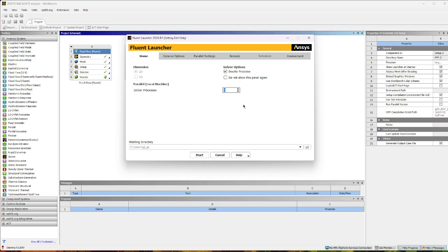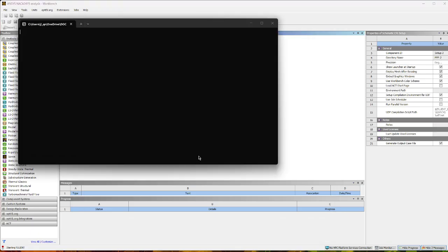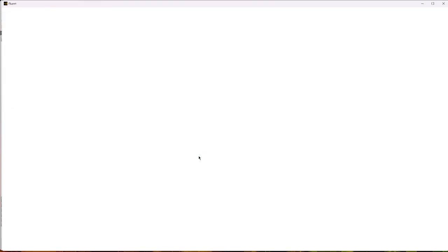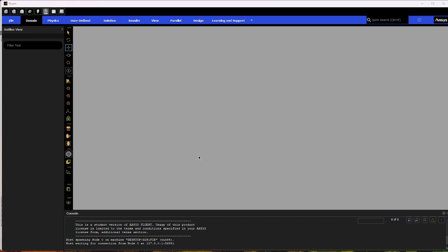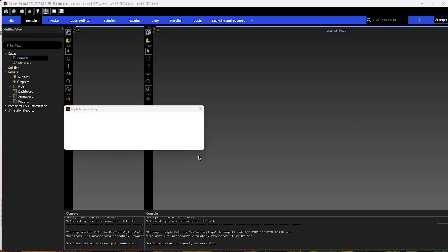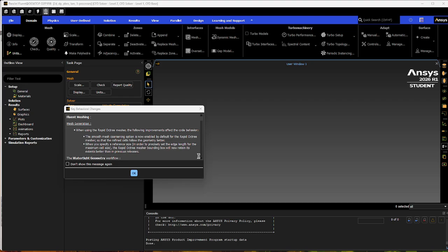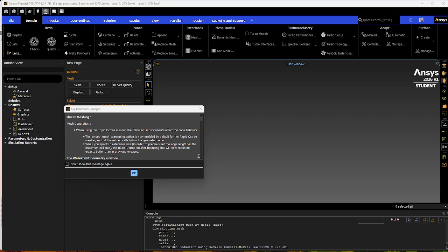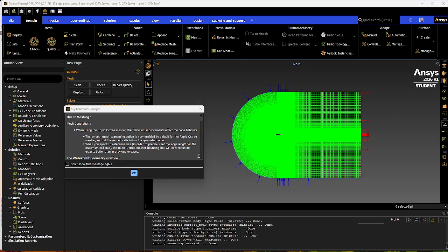The reason being it's going to take a long time to process this data because, especially with the higher angles of attack, you need a lot of iterations to calculate in order to reach a good convergence. For the lower angles of attack, you reach convergence pretty early, but I think it only happened for me at the 21 degree angle of attack. I needed like 3,500 iterations for the calculation, and it still didn't converge, but it gave me a pretty accurate answer. So the more iterations you do in that case, the more accurate your answer is going to be.